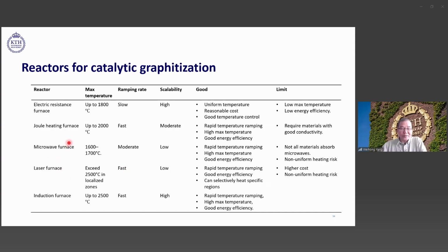People say they might be not only good for heat treatment, but also for improving the properties of the graphite. But in general, what we need is heat treatment. What we need is temperature, more than anything else, whether for microwave or laser. If we have enough temperature, up to 1800 degrees or even higher, you will for sure get high quality. Other influences, like microwave and laser, should be very, very limited.